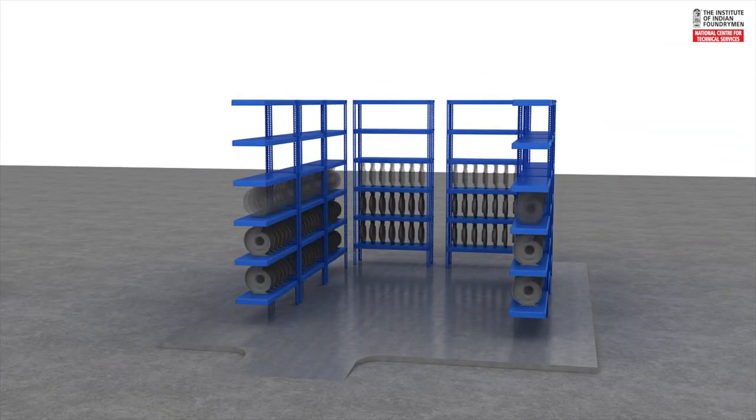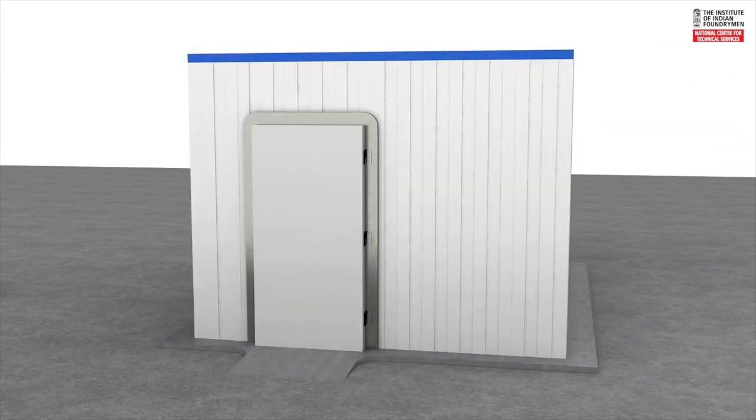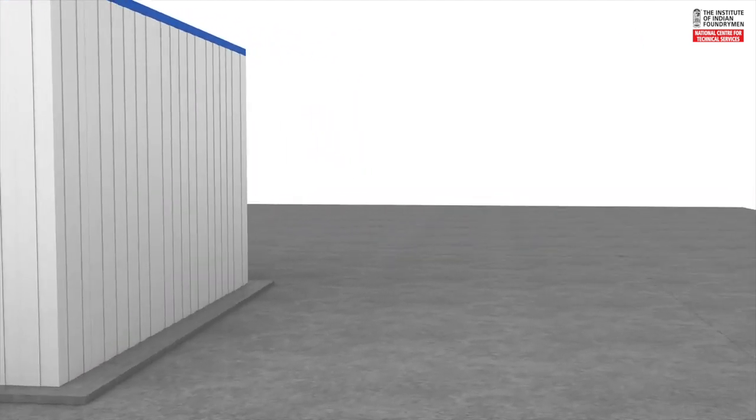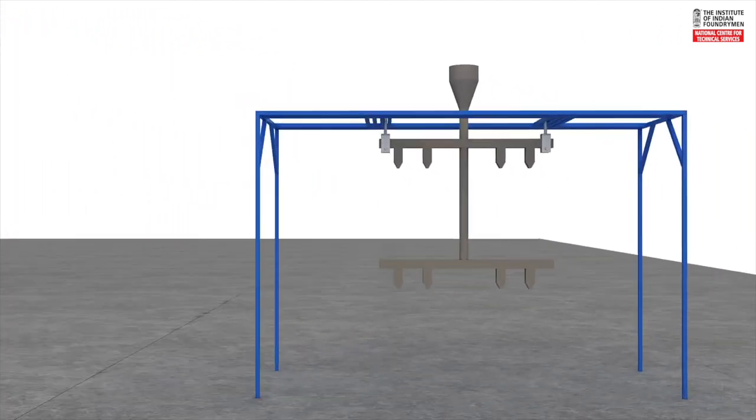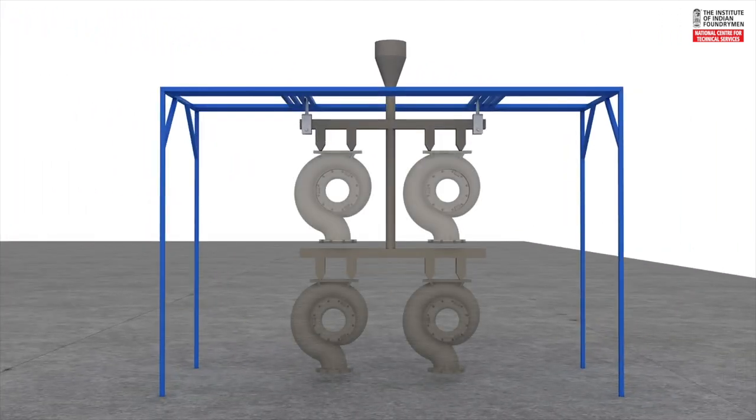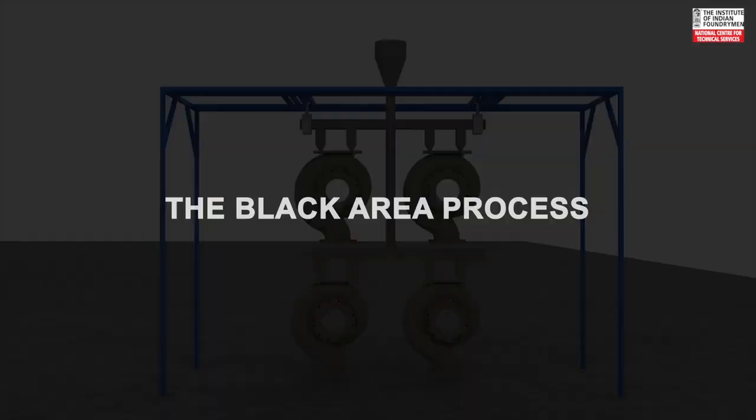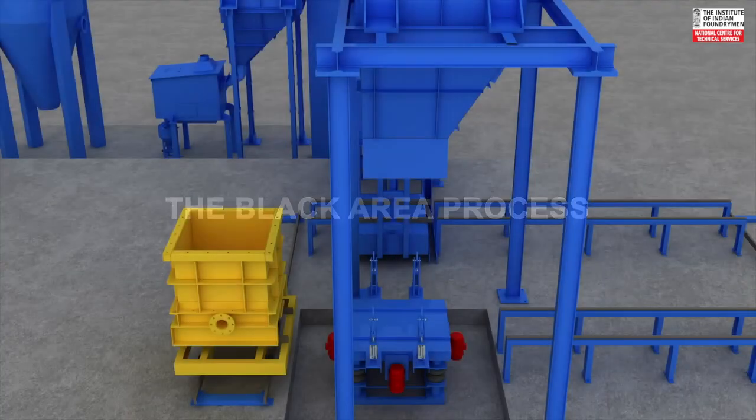It is as easy as that. Since there is no binder, the knockout and other problems are eliminated. The surface finish is delivered by the die and simultaneously by the first coat of the coating. So sand properties or sand fineness does not affect the surface finish at all.